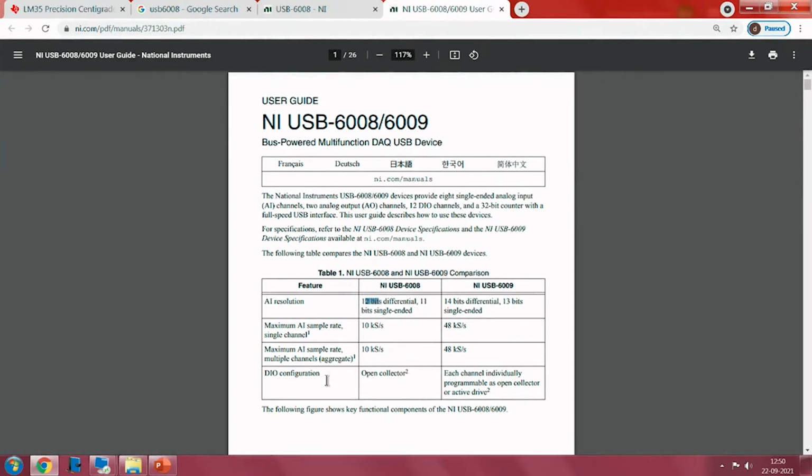Yesterday's class we discussed an 8-bit ADC. If we are using NI myDAQ, it probably has an 8-bit ADC. Or if you are using any data acquisition device with an 8-bit ADC, whatever we discussed yesterday will work out. Of course, the generalized concept of interfacing and the selection of ADC is pretty much the same, provided the formulas or the resolution of the ADC are slightly changed. So, based upon the reference that you selected, the number of levels that the ADC will have depends upon the resolution of your ADC.